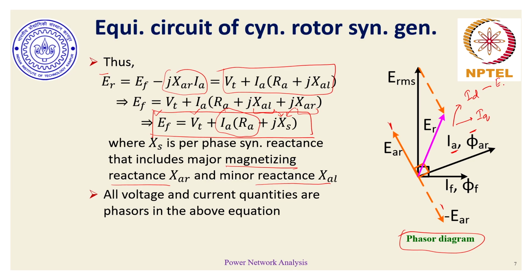So let's say if we mark the EAD as the armature reaction voltage because of the direct axis current, and EAQ as the quadrature axis reaction voltage because of quadrature axis current, how would these reaction voltages look like for a given salient pole machine? Now it is for sure that the induced EMF and the corresponding reaction voltage don't align with each other. They are phase apart from each other.